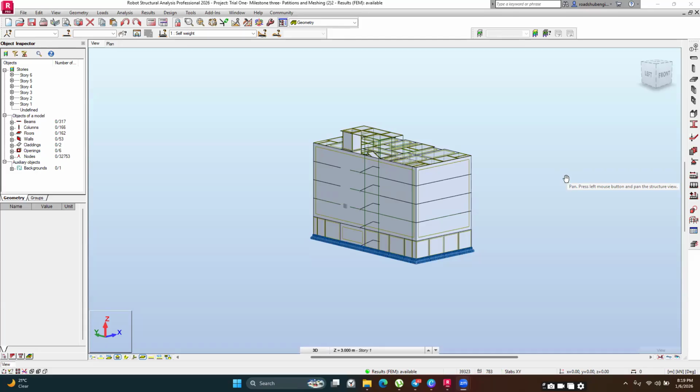Some of the members are not going to pass the design, okay, due to the nature of the forces or the magnitude of the forces they are exposed to. And when that happens, you have to resize them, or sometimes you may even have to remodel some bits so that you can probably orient them better or just optimize them if you need to. Okay, so that's the stage you are getting into. We are done with the modeling bit, so we are going to go into analysis first.